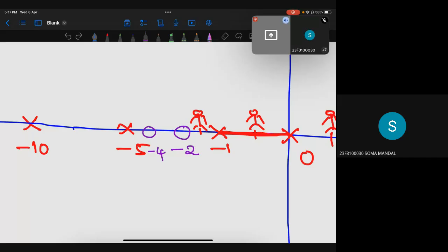Now you have crossed this zero at minus two, and if you are here, now you check. You are somewhere here. If you check how many you have: two poles plus one zero, that is three, an odd number. Then this is part of the root locus. That is true even if you are standing anywhere between on this point.